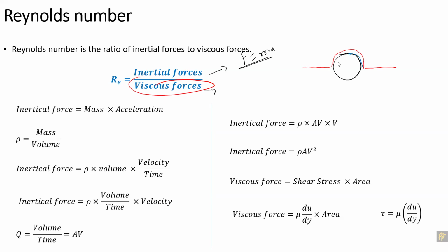So you can expect that the flow should be separating from this point or this point, depending on the Reynolds number. That's why as we go to a higher Reynolds number, you will see that the flow will detach from some location. So it may go this way, it may go this way also. Depending on the Reynolds number, maybe it will separate from here, it will separate from here. And we can find out this location exactly on the circular cylinder based on the coefficient of pressure value.